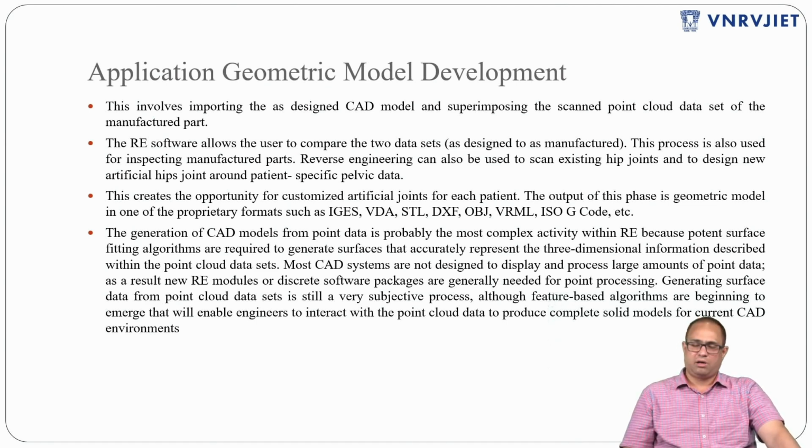Whatever file is obtained can be converted into different formats as per our requirement, either IGS or VDA or STL or DXF format or OBJ format. The generation of CAD models from the point data is probably the most complex activity within reverse engineering, which requires much skill to perform.